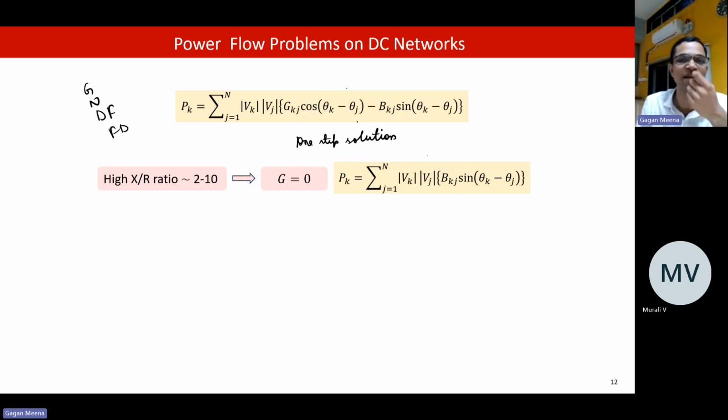Let's say we have to take a decision for each 15 minutes, right? For each 15 minutes, we have to dispatch the generators. So we need to do market clearing. There is a real time market. You know, we have a day ahead market and a real time market.